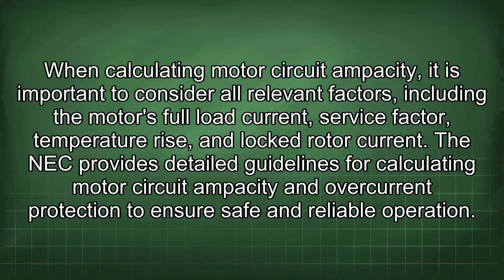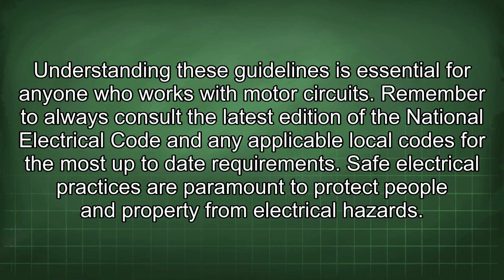When calculating motor circuit ampacity, it is important to consider all relevant factors, including the motor's full load current, service factor, temperature rise, and locked rotor current. The NEC provides detailed guidelines for calculating motor circuit ampacity and overcurrent protection to ensure safe and reliable operation. Understanding these guidelines is essential for anyone who works with motor circuits.